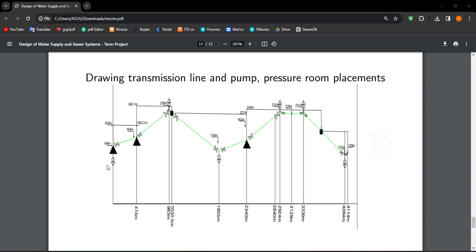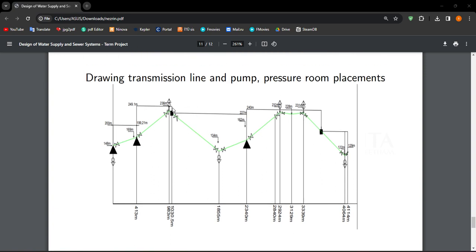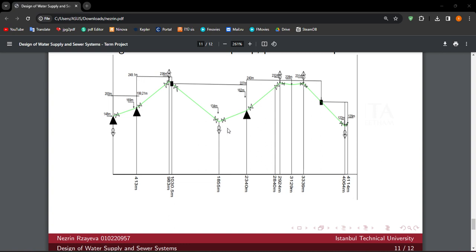This shows the air release in the opening of the pipe system, and I showed the rectangular one as the pressure tank, which is located there because P divided by gamma max must be less than 100 meters. Otherwise, it can explode our pipe. Also, at the same time, P divided by gamma minimum, the minimum pressure head, must be 4 meters, otherwise it cannot flow in the pipe.